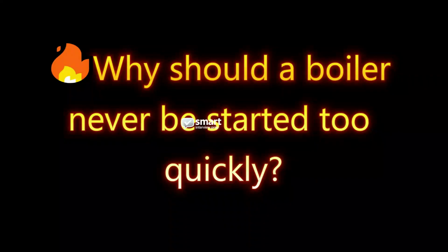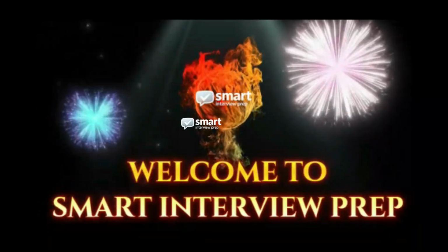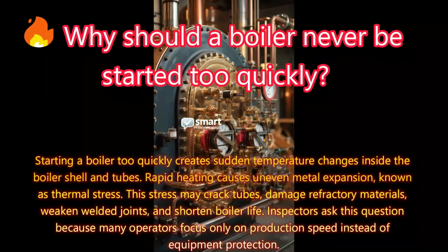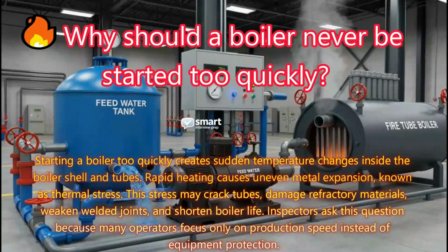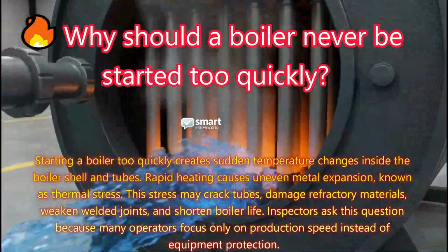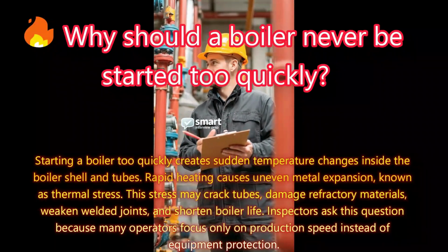Why should a boiler never be started too quickly? Answer. Starting a boiler too quickly creates sudden temperature changes inside the boiler shell and tubes. Rapid heating causes uneven metal expansion, known as thermal stress. This stress may crack tubes, damage refractory materials, weaken welded joints, and shorten boiler life.